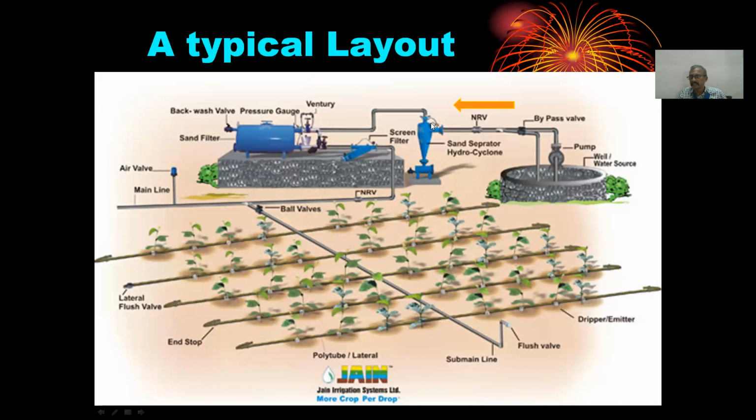This is the first filter, called the sand separator. The sand separator is also called a hydrocyclone. You would have studied cyclones in your processing courses, and this also operates on the same principle. The principle of operation you will study in a little more detail in the coming slide. But at this stage, keep in mind that the sand separator just filters the sand.